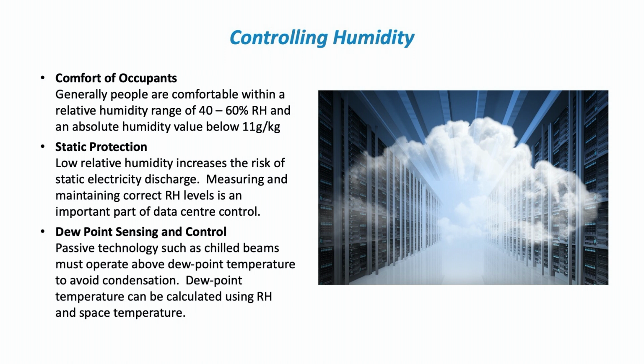Again, those of you doing data centers, humidity has an effect on static discharge. So if you've got a buildup of static electricity and you have very low relative humidity levels, then static discharge is more likely. Static discharge can damage circuits. And so if you have static discharge within a data center, what you can do is damage the computers, and that can obviously have some quite damaging implications.